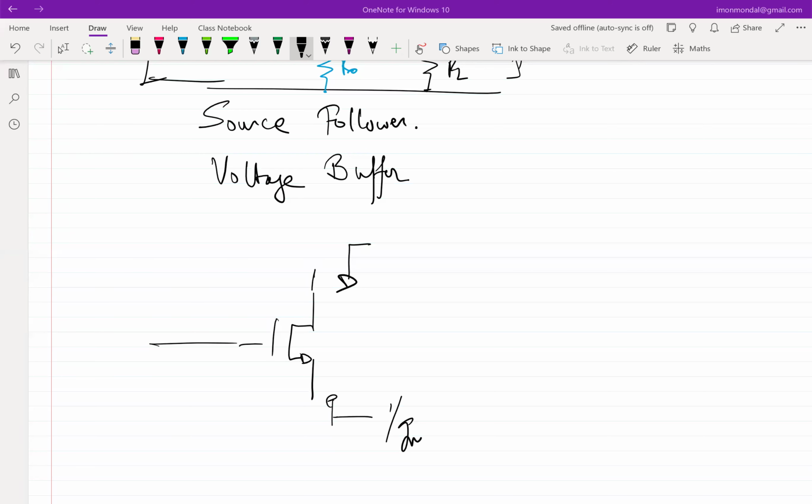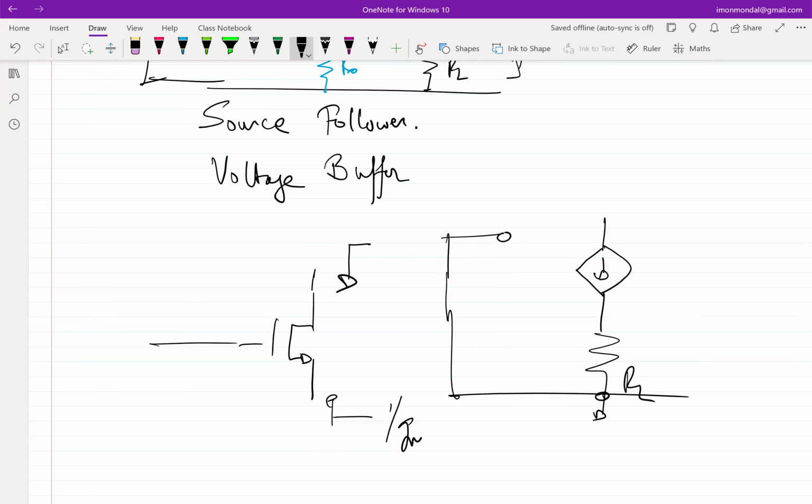So in the incremental sense, the source is grounded, right? So I am talking about a pristine transistor, with nothing connected to the source. On the input side, what are you going to do? Okay, so let's assume the resistor is also connected. Let's do this. So again, the input is grounded. And what are we looking at? We are looking at putting a test voltage source here, right? We're trying to figure out the drain impedance.